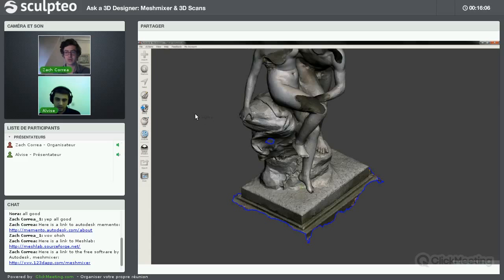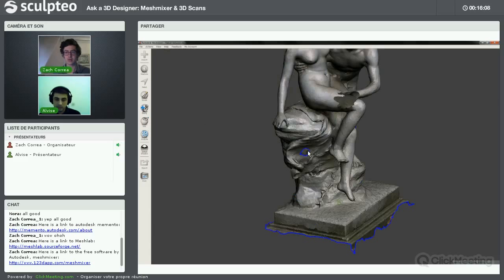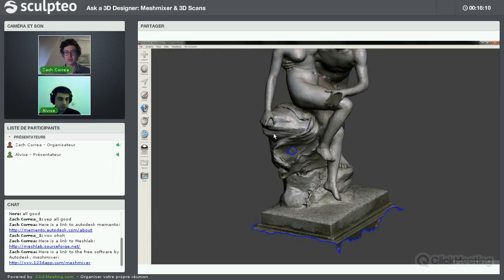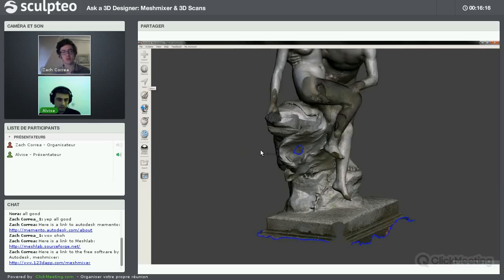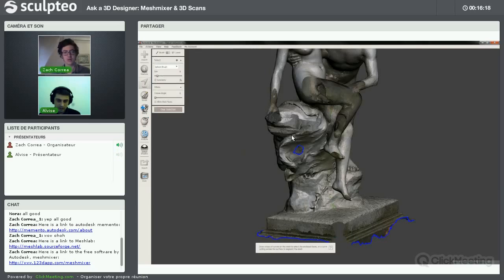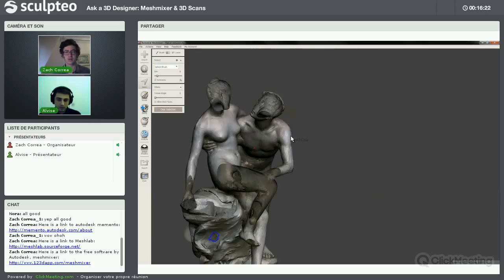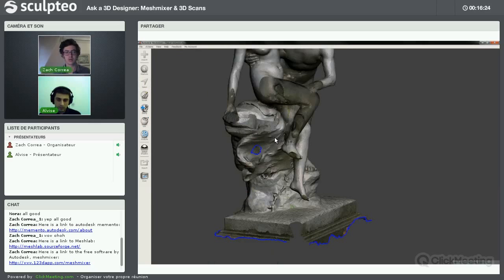There are a couple of ways again to do this. I'm going to show you both. First one, I take it. Wait, actually, first of all, I want to see the edges of the triangles. So I'm going to tap W on my keyboard, and the edges appear.